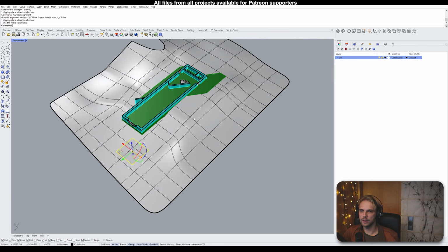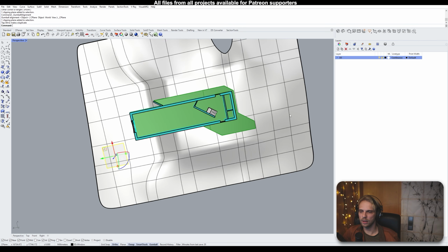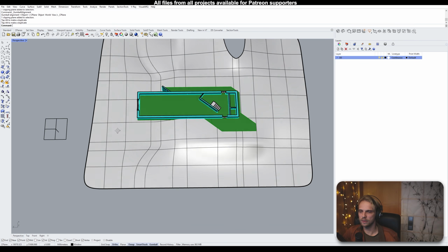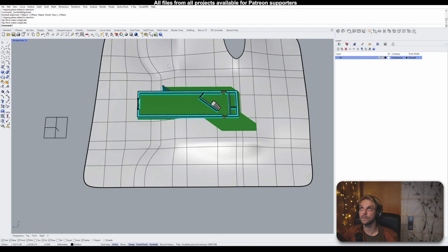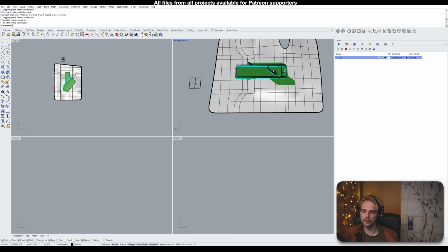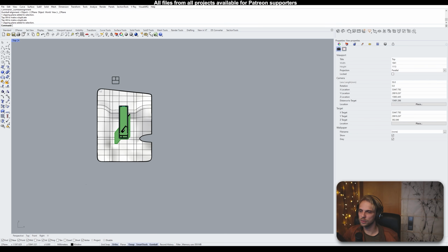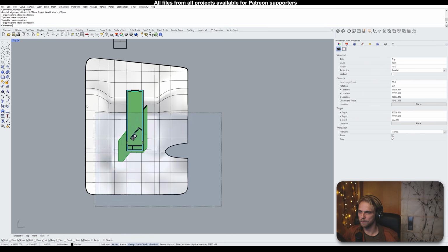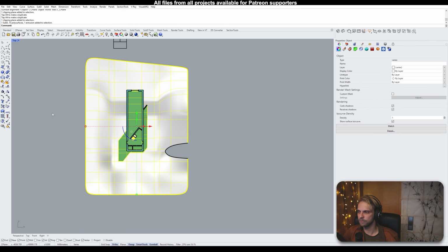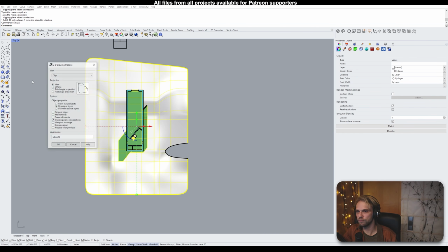This is going to be how the site looks like. Not the site, sorry, how the building looks like as it's being clipped at that particular height. And then as per usual, we select the clipping plane, we go to its properties, and we choose top to be clipped as well, because that is indeed going to be the projection that we will be clipping. I will select everything, type in make 2D.